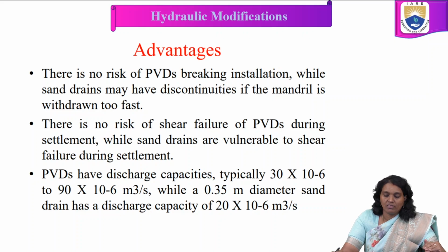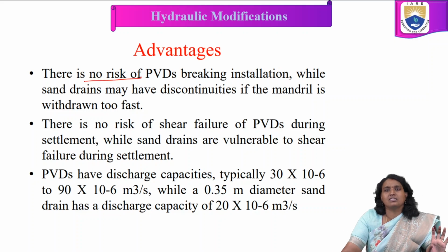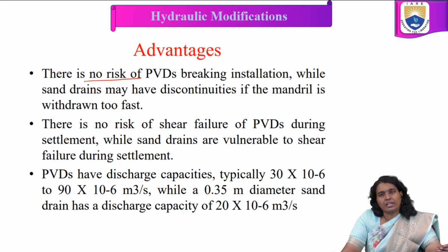In this case we are using the same equipment, but with PVDs that kind of breaking at the time of installation is avoided. In the prefabricated vertical drain procedure, there is no risk of breaking during installation compared to sand drains, which may become discontinuous if the mandrel is withdrawn too fast.